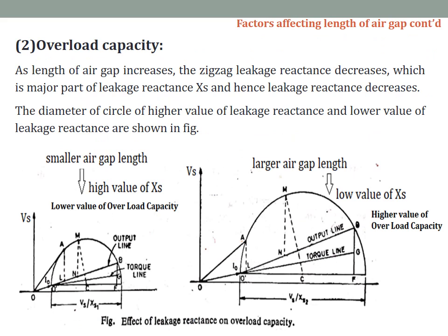Now coming to overload capacity. As the length of the air gap increases, the zigzag leakage reactance decreases, which is a major part of the leakage reactance excess, and hence the leakage reactance decreases. Understood? As the length of the air gap increases, the zigzag leakage reactance decreases.